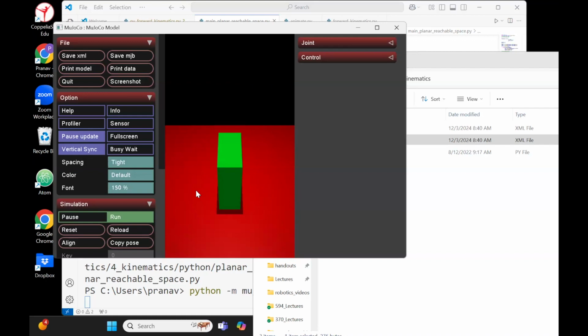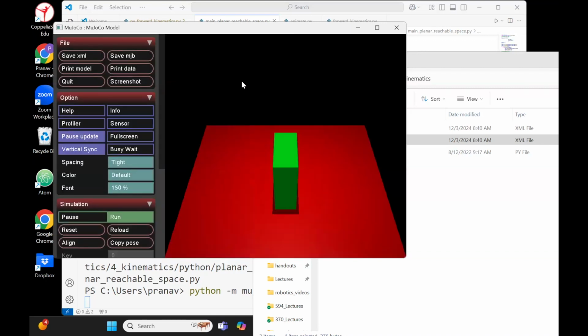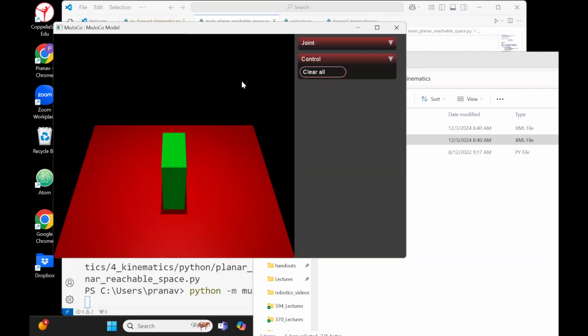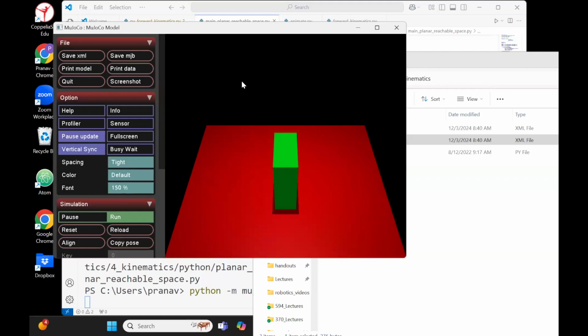Okay, now here's the thing you can do. You use this in this mode. This part is not very useful, I think, at least for now, so you can actually get rid of it. I think if you press Shift Tab, it goes away. If you want to drop the UI on the left side, you just press Tab and it drops away. Tab gets it back and forth, and then Shift Tab will get the right side. Okay, so we don't need the right side. We might need the left side, so I'll keep it.